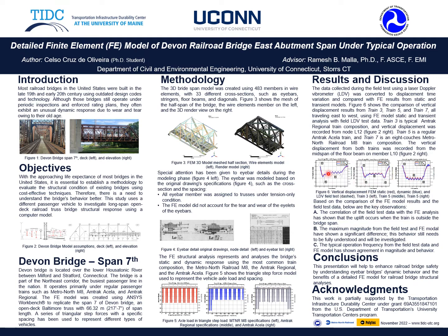And lastly, we were able to match the working frequency. By matching that working frequency, you can identify where the uplift is happening, where the maximum load is happening, all those things. That's pretty much what we did so far. And the main advantage of a good finite element model is that it can help us identify unusual bridge behavior that we might have, like, for example, the uplift that we were not expecting. Assuming that the finite element model is the perfect world, it will be without the uplifting.